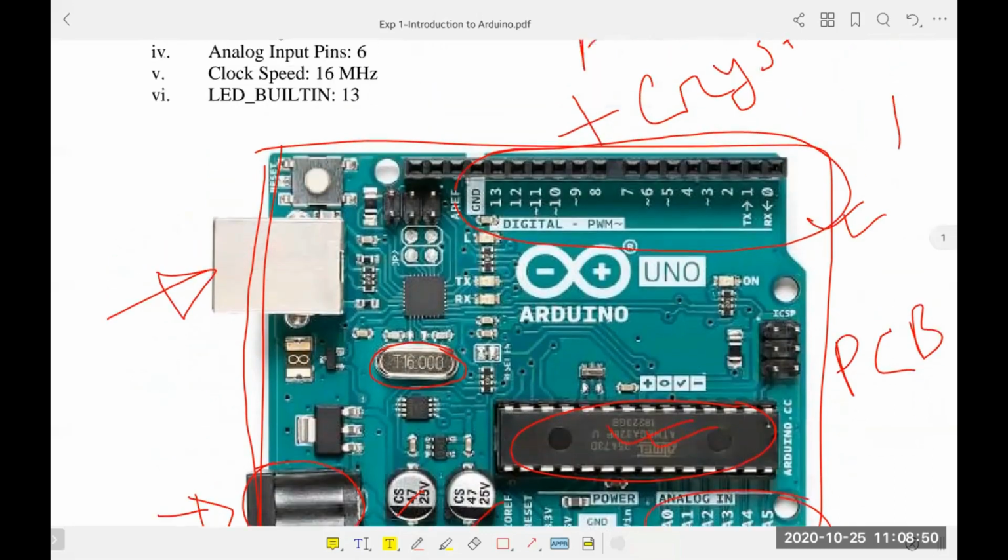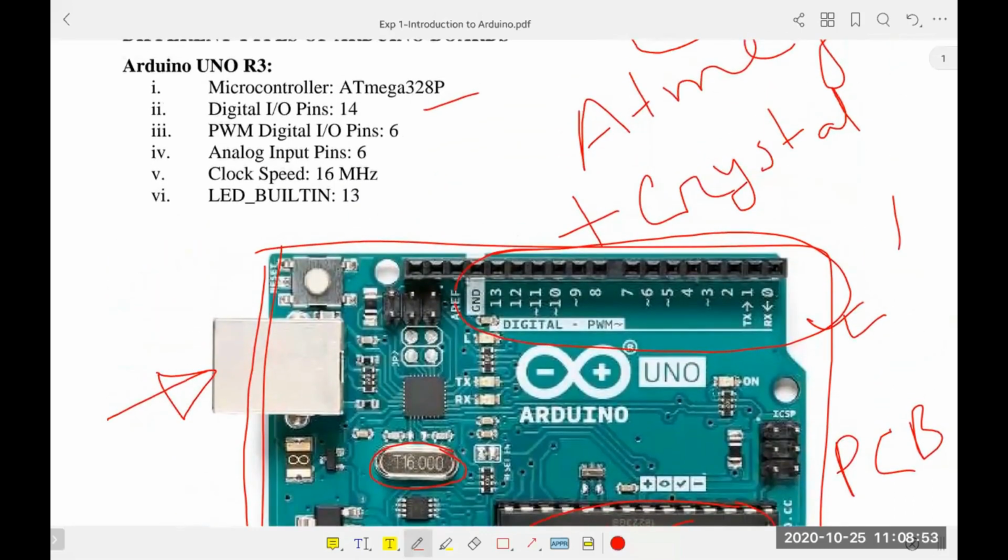I think you know what analog and digital are. Analog can take any values, and in our case, let's say you are using an analog pin, you are going to read some voltage value from 0 to 5 volt. So this voltage could be 5 volt, 4.9 volt, 4.98 volt, 4.6 volt. There are different values, and these are analog quantities. If you want to read this type of values, then obviously an analog input pin will be your choice.